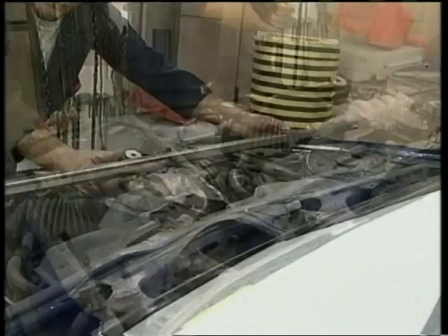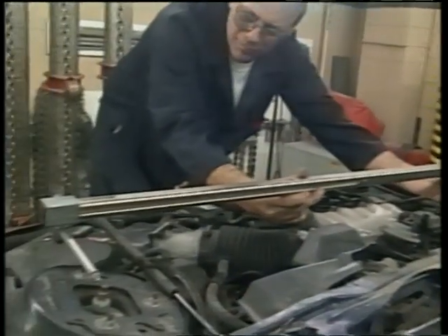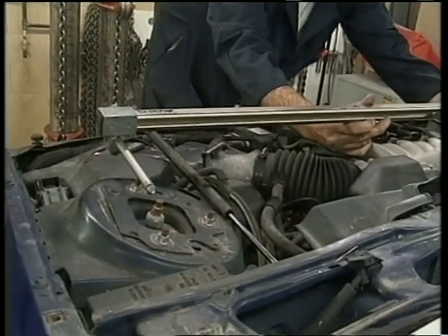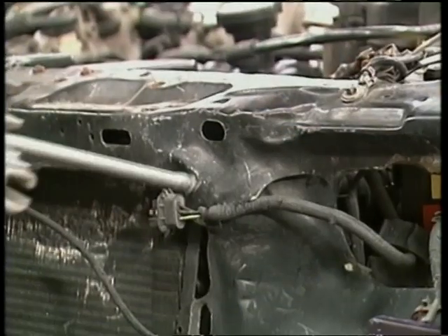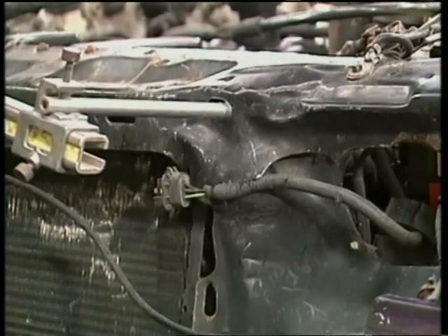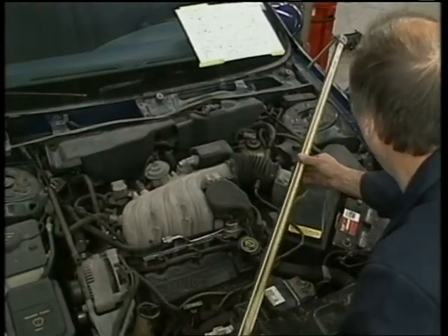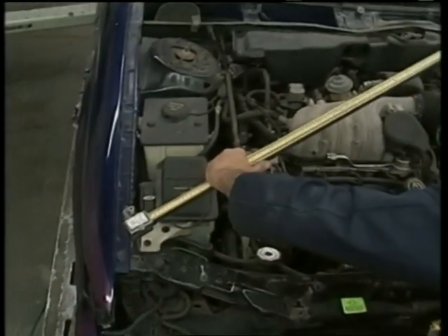The best areas to select for tram bar measurements are attachment points for the suspension and mechanical parts. These points are critical to alignment. Reference point holes are frequently larger than the tip of the tram bar. To measure accurately, place the point in the holes from edge to edge.